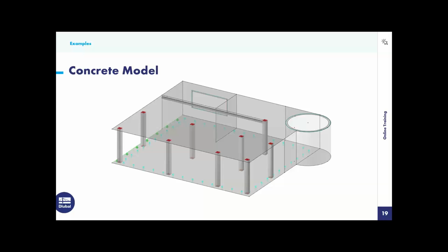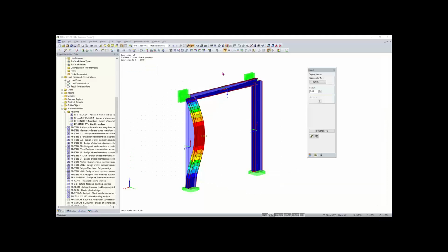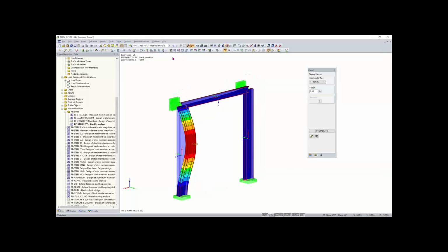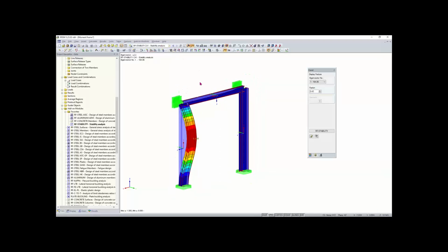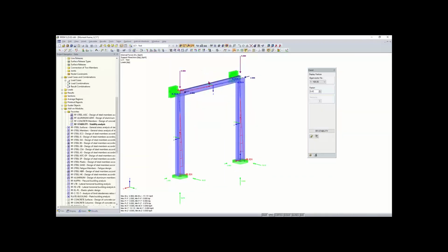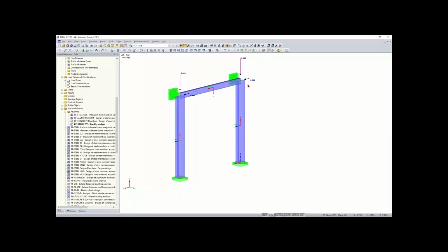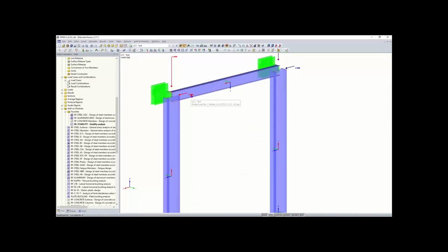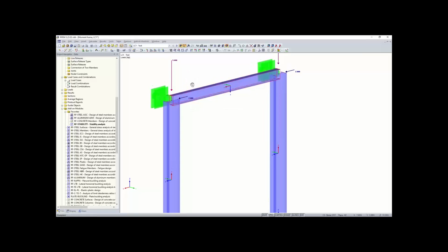Yeah, I think I'll just explain to the user quickly that the lateral loads can be applied the same way as gravity loads. So Alex has been applying loads in the global X, Y, and Z directions. So lateral loads would be in the X or Y directions. You can see here 2 kips, for example, is in the lateral direction. So that should answer the question.